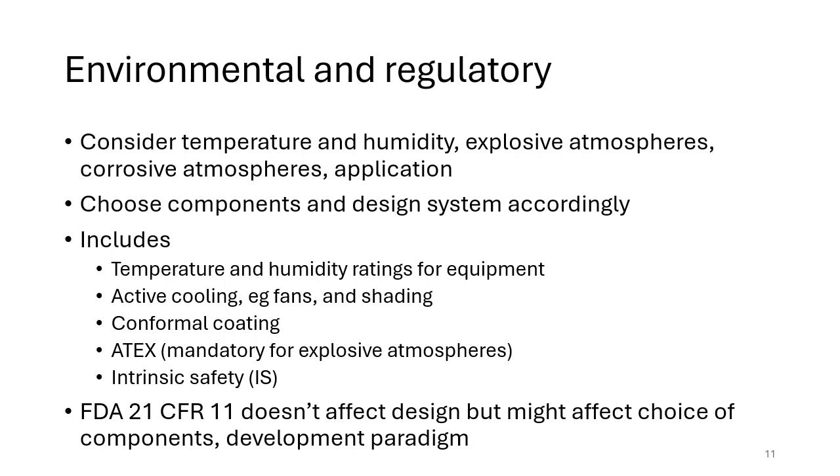And all of this will depend on what the application is, and the application itself may have its own particular requirements as well. So you would choose components and design the system accordingly. For example, for explosive atmospheres, you may need something that is ATEX Zone 2 compatible. You might even need to go to ATEX Zone 1, and that might involve the use of intrinsic safety. Intrinsic safety often uses barriers which prevent a dangerous voltage and current getting out into the field and prevent the possibility of a spark that might ignite an explosive environment.